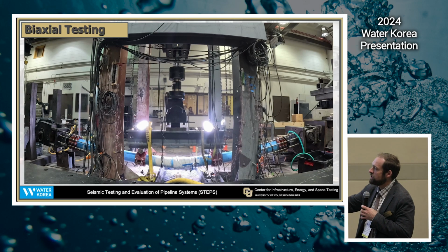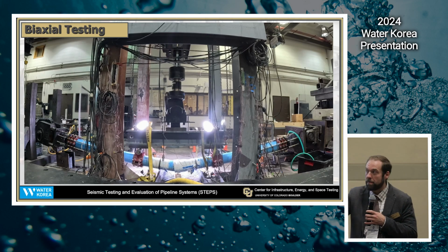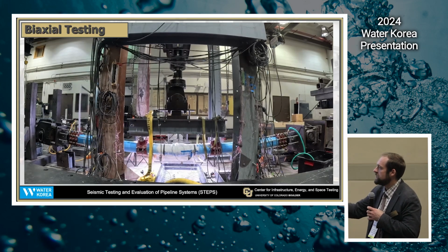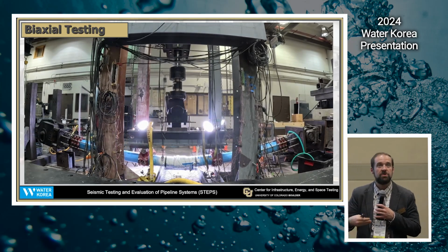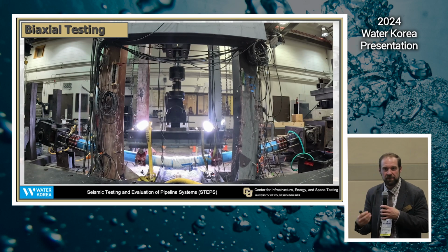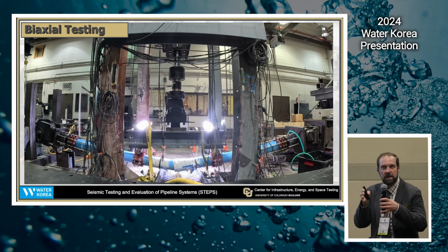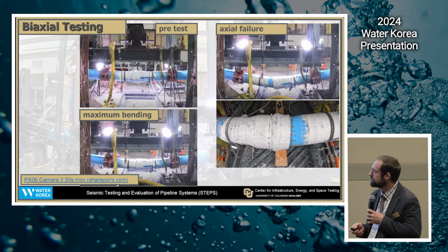And then we also have strain gauges along the pipe length to measure localized strains on the pipe barrel, as well as displacement devices across the joints vertically in a number of different areas. And so we're working to try to standardize the measurement techniques we need to take to get that key information that allows us to systematically sort of classify these different systems for levels of ground.